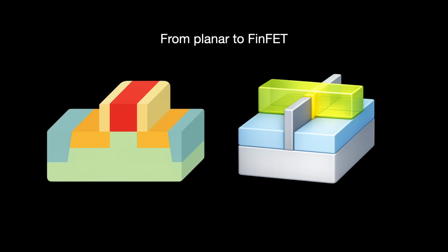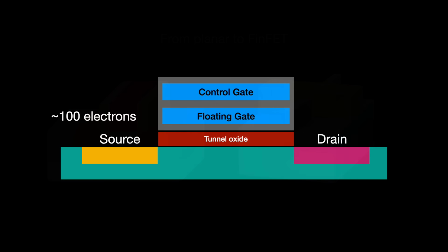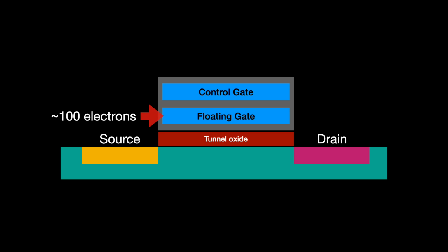But then there are the flash memory related issues too. The flash memory cells are now so physically small that their floating gates contain about 100 or so electrons for a threshold of 1 volt. It takes fewer electrons leaking to cause significant degradation. And with the tunnel oxide layers so thin now, that is way more likely.